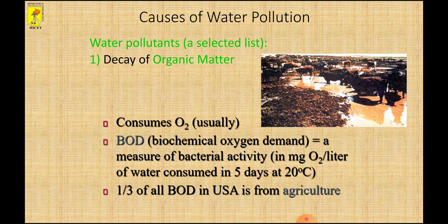BOD is the amount of oxygen required for biological decomposition of organic matter present in water. So BOD is called biochemical oxygen demand. The reaction period is taken as 5 days at 20 degrees Celsius for all practical purposes, so it is also written as BOD 5. The rate of oxidation and the demand depend on the amount and the type of organic matter present in the river water.